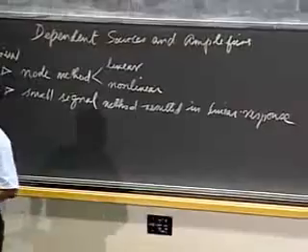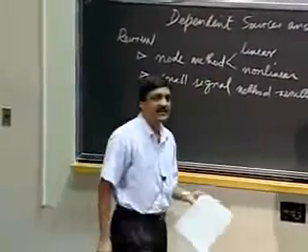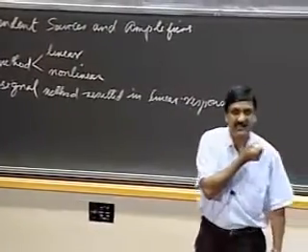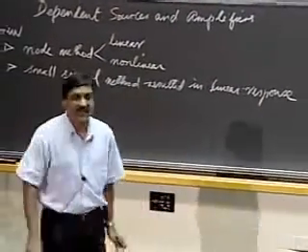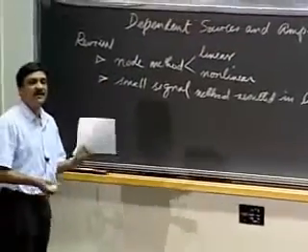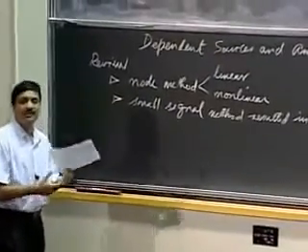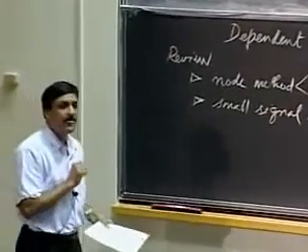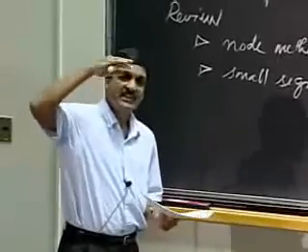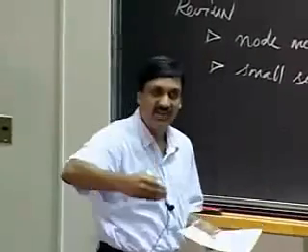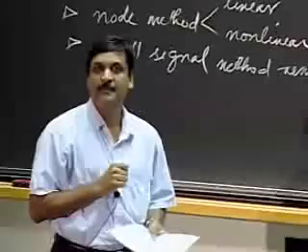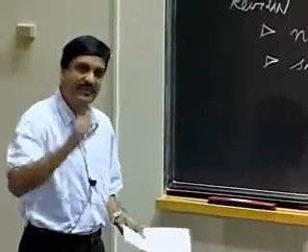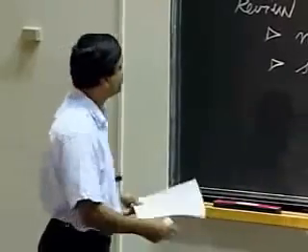and as an example, I showed you how I could take a highly nonlinear device like the garage door opener LED and using that build a pretty nice transmitter that would transmit music, and as long as they kept the signal small and operated the device in a region where its transfer curve was relatively smooth, and I biased or set the operating point appropriately, I would get a linear small signal response. Okay.